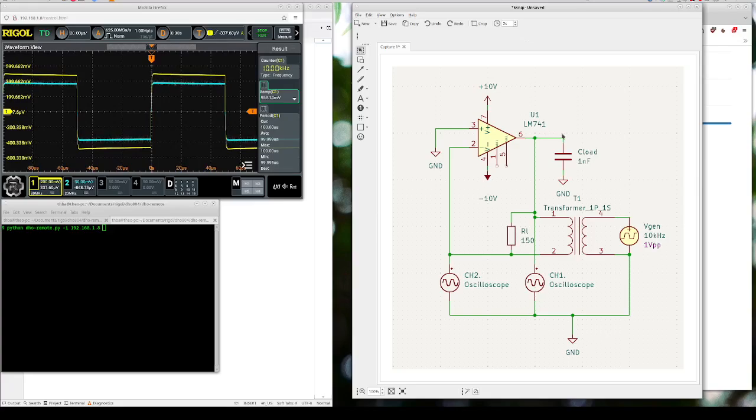The setup for such is that you need a transformer. More about it later. Again, you need a square wave signal generator to drive that, and the output of that transformer will be put in series with the feedback loop. The idea is that the signal that develops here is basically between the output and the input of the operational amplifier. I used the 741.